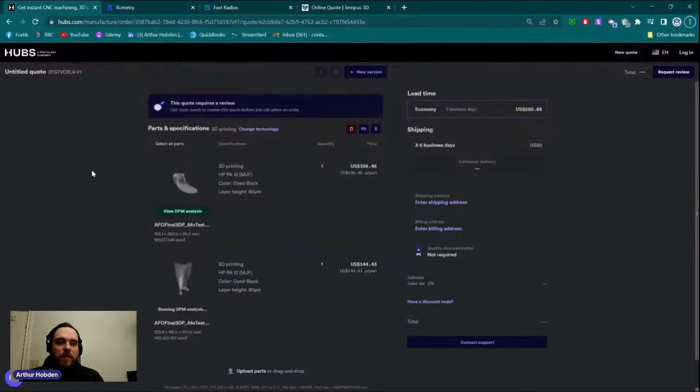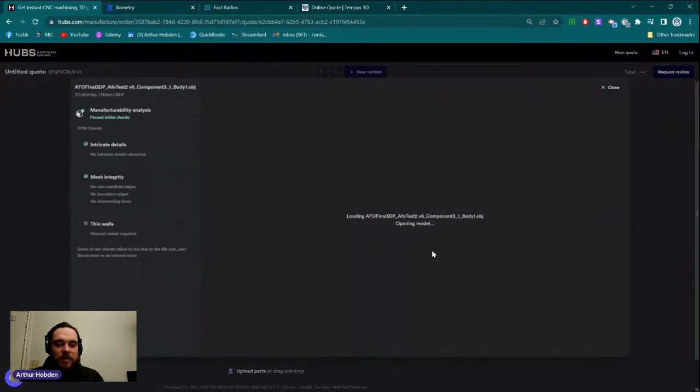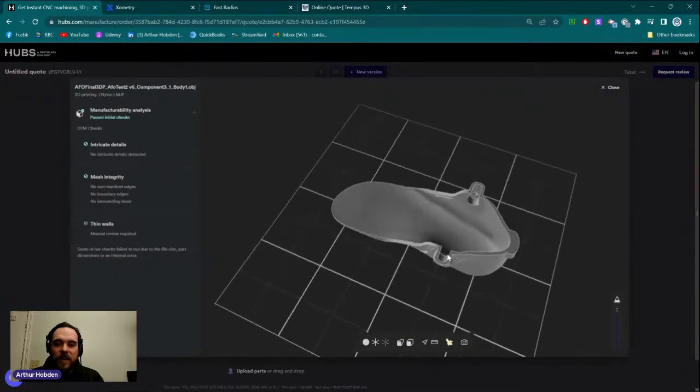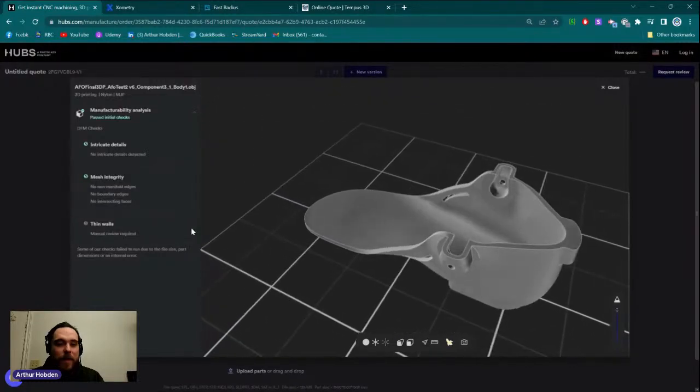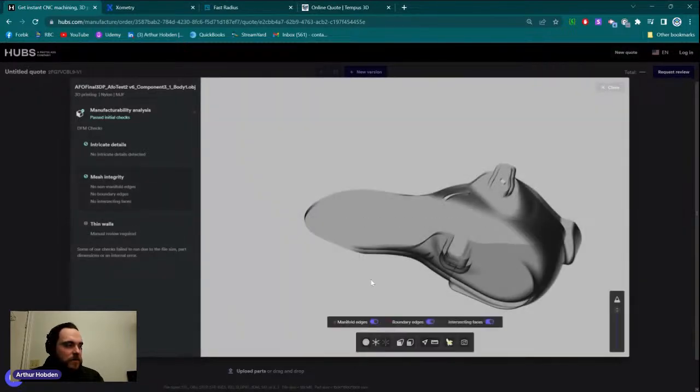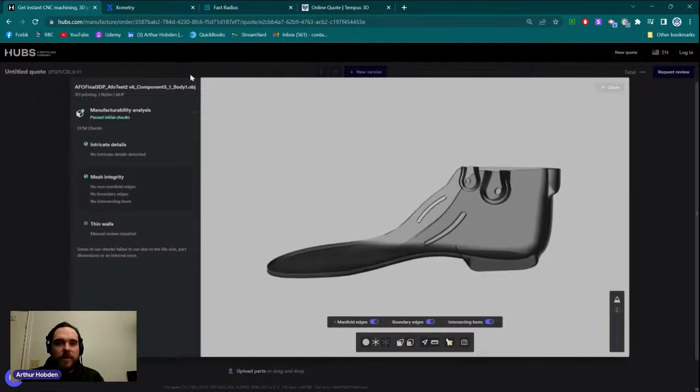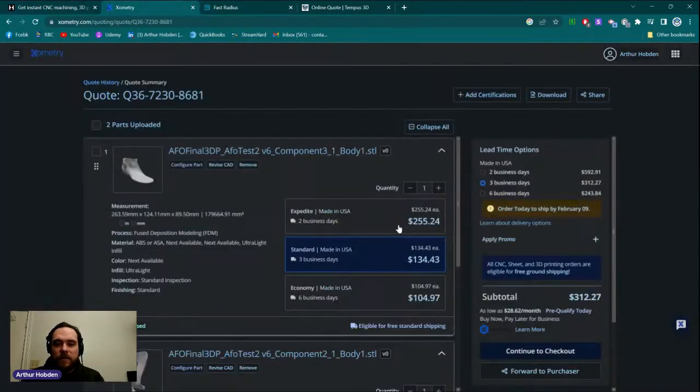So what I've done, guys, is I've gone online to 4 different online manufacturing centers that have 3D printing. So hubs.com is one of the big ones, and I uploaded these 2 parts, and you can see that I can get an instant quote: $106 to print this, $144 to print this. You can go into these and you can change things like the material that you're using, what scale it's at. Is it dyed black? Is it polished? Is there any bad thin walls? They actually review it for you. So that's really exciting. And then Xometry at 255 or 134.